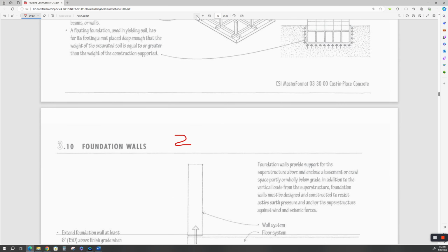Just cast pockets in with this wall, and that's a part of that. And then the masonry can set on pockets. That's expensive. That's an expensive detail. Or what you can do is you can put a ledger beam across here, like a lintel, and fill that gap in.